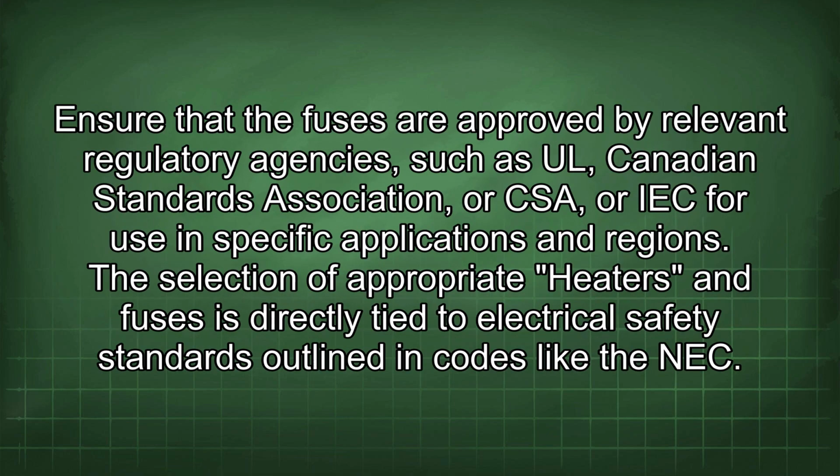Ensure that the fuses are approved by relevant regulatory agencies such as UL, Canadian Standards Association, or CSA, or IEC for use in specific applications and regions. The selection of appropriate heaters and fuses is directly tied to electrical safety standards outlined in codes like the NEC.